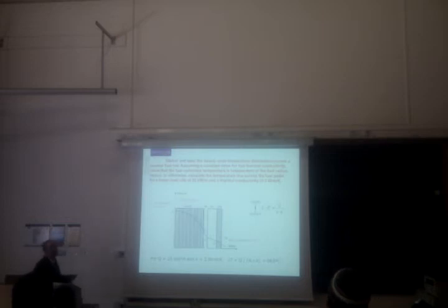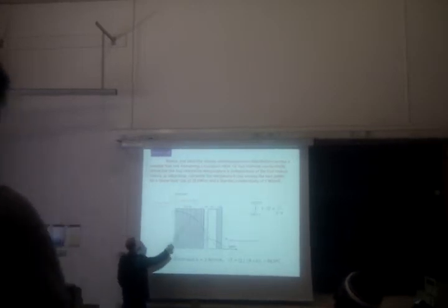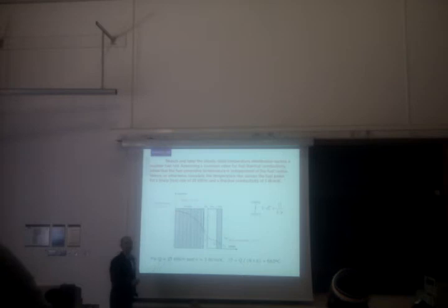Steady state temperature distribution, we've gone through this ad nauseam. We know that the highest temperatures are in the middle of the pellet. We have this parabolic profile down towards the edge of the pellet. Quite a large temperature drop across the gap. Why is that? Why is the temperature drop so high across the gap, given that the gap is so very, very small?